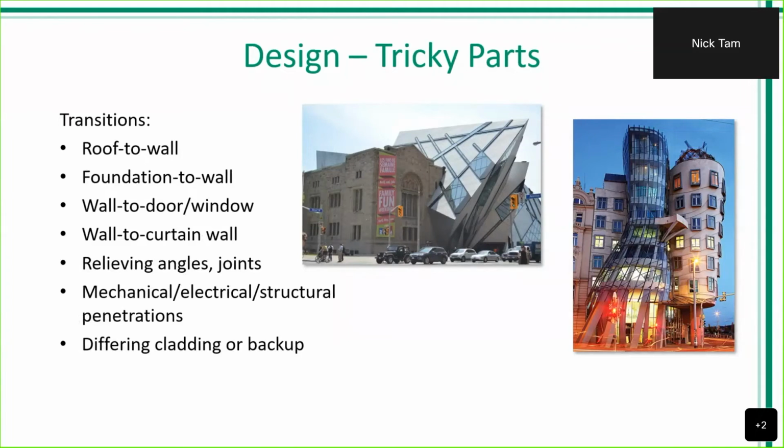I think the picture on the right is a really good example of where we have a lot of window openings, we have a lot of different building materials, and we have an awkward set of joints that I don't know if the contractor was going to be able to get good accessibility to that joint to ensure that we have the proper segmentation that we need to have an airtight structure. So we want to make sure that we have proper segmentation when possible, but we're also not going to tell you to not use your imagination and create the beautiful artwork that is these structures.